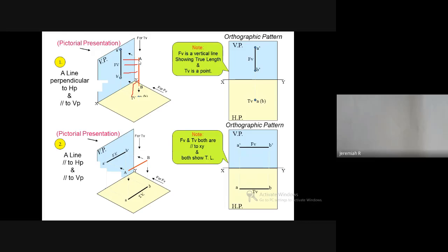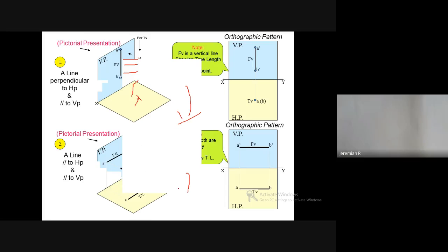In the top view you also get a straight line AB. Top view means you should not mention the dash. Whatever you are getting in the horizontal plane, you have to rotate clockwise 90 degrees. So what is the rule you have to follow? The top view is projected on the horizontal plane, and that you have to rotate clockwise 90 degrees. So this is case number 2.